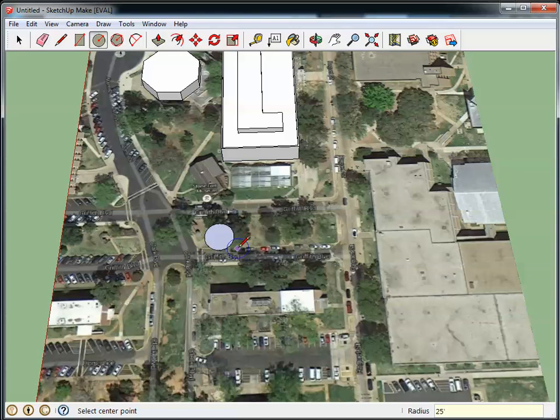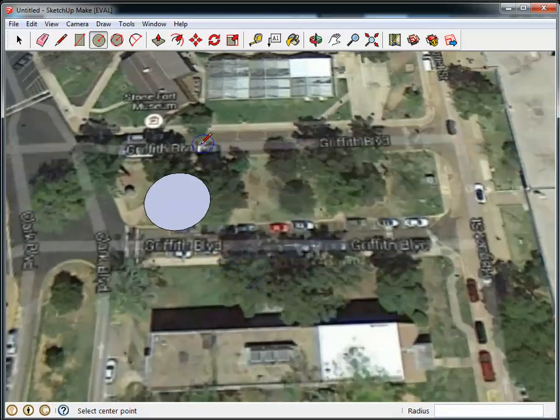We'll resize it to a 50-foot dome in diameter. At that point, you can grab the rectangle tool and click on the edge, and that kind of helps you highlight the center. So if you hover around the center, sometimes that center doesn't appear, but clicking on the edge first does.